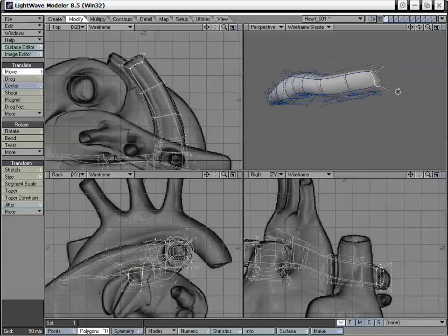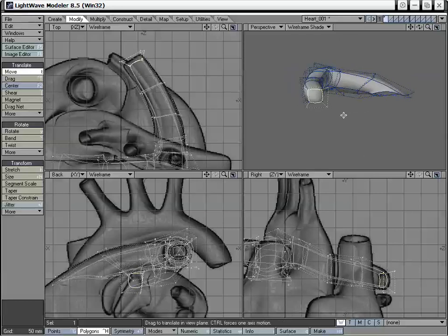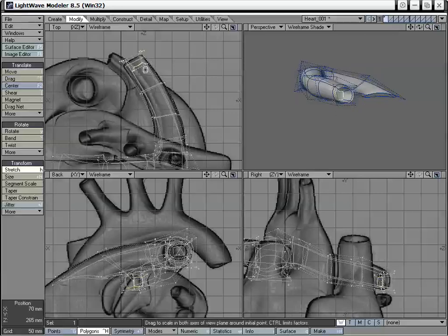T to move that down, and now we want to stretch that just a little bit downward so that it's kind of tapering. Shift F, right mouse click, H, stretch it in just a little, and then Shift F, right mouse click, T, move it inward, and stretch it again, just so we can create that temporary hollowness within it.